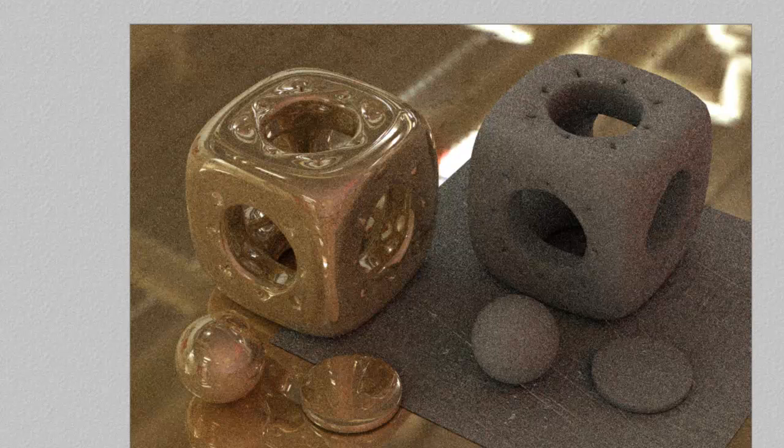Okay, I've let that have a little bit of a render, and there's a couple of things you should notice. First of all, it's a bit noisy, but then again we're only using low rays per pixel, and the other thing is that we've lost the colour from the HDRI backdrop. That's sort of been reduced significantly. To recover the colour then, we'll switch boost light on and have a look how that looks.